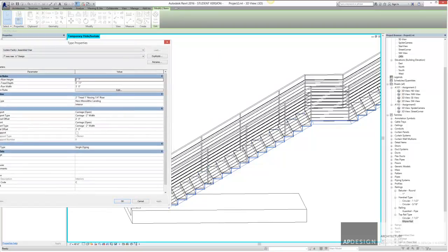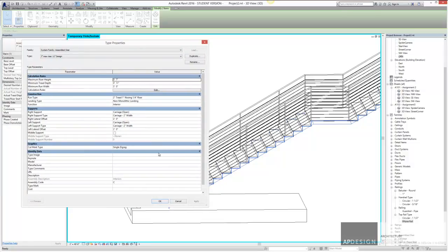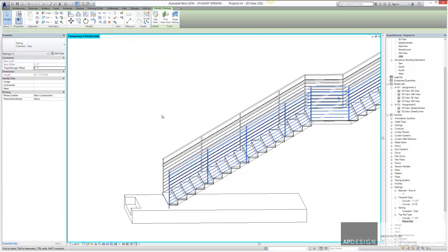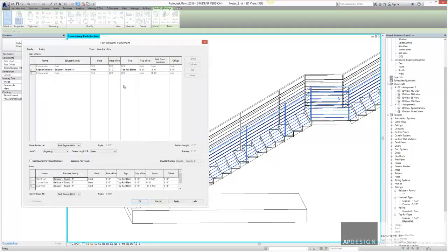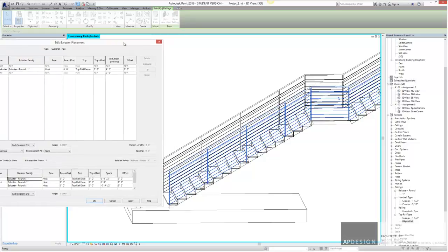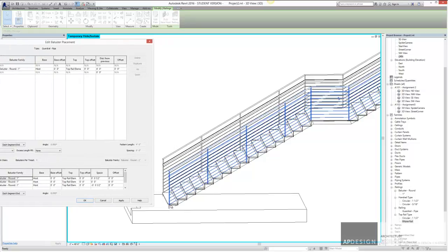So to do that, I'm sorry, I clicked the wrong thing. Select the railing. We're going to look at the baluster placement, and we're going to start seeing what these numbers really do. So down here at the start, there's maybe this ½ spacing, and essentially I think that's so it actually gets onto the stair appropriately. And then there's this kind of random 4 feet.